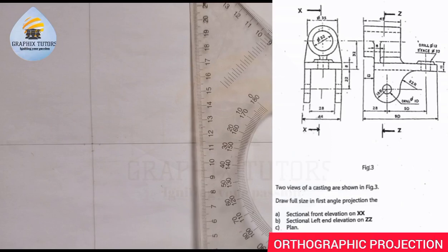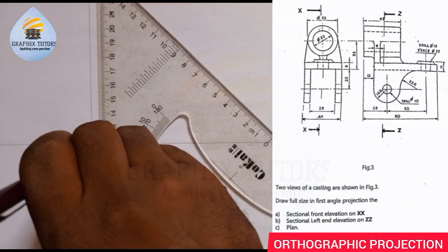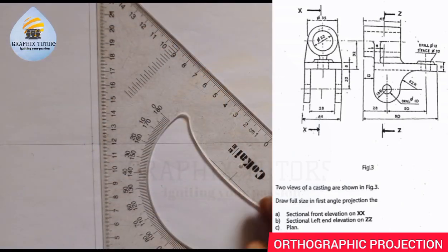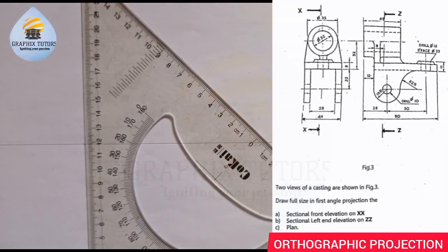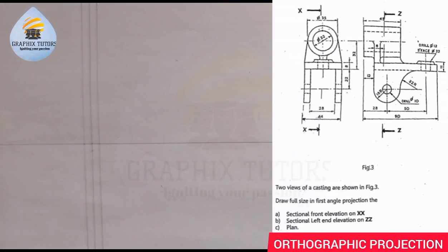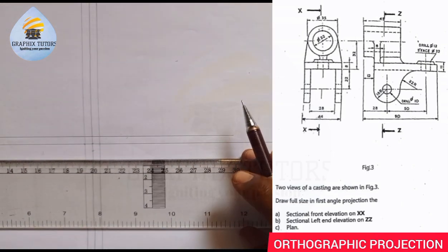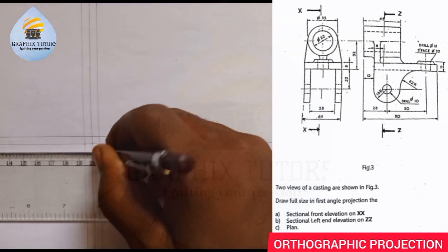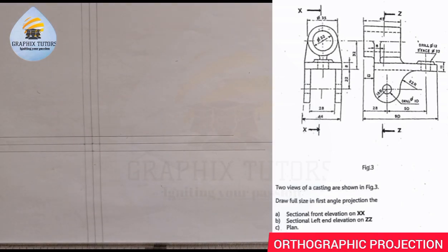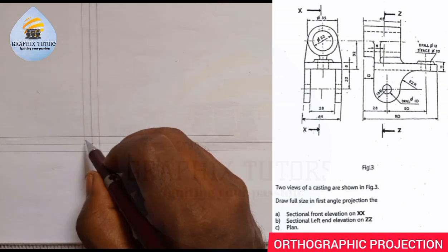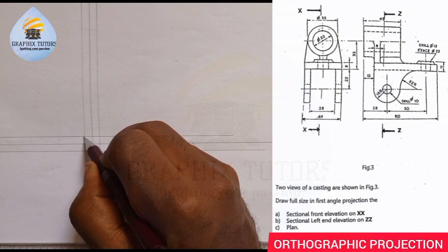Then I'll take my set square and my T square working hand in hand. Move it to this point. I will draw my vertical line, faint line. Move it to the next point again. I will draw another vertical line. Then I will come here, I'll draw this also. And I'll come here, I'll draw this also. You can see that. So I've completed this. All these points you see at the top outer corner will be my reference points. This is where I'll start taking my measurement from.